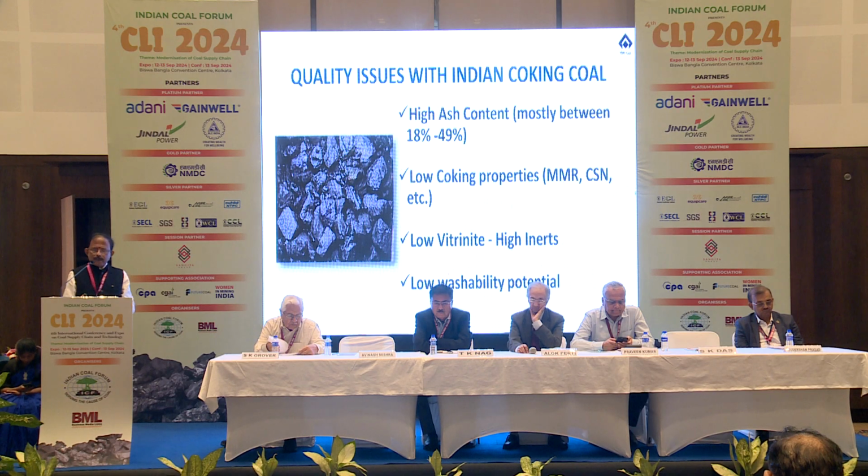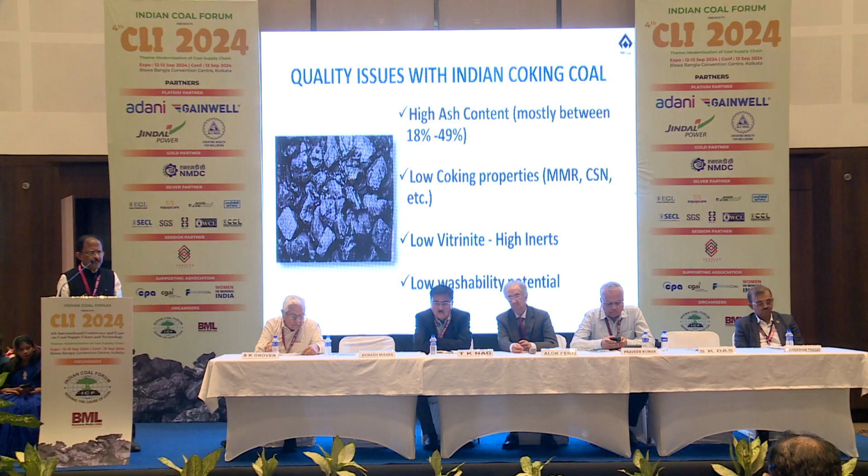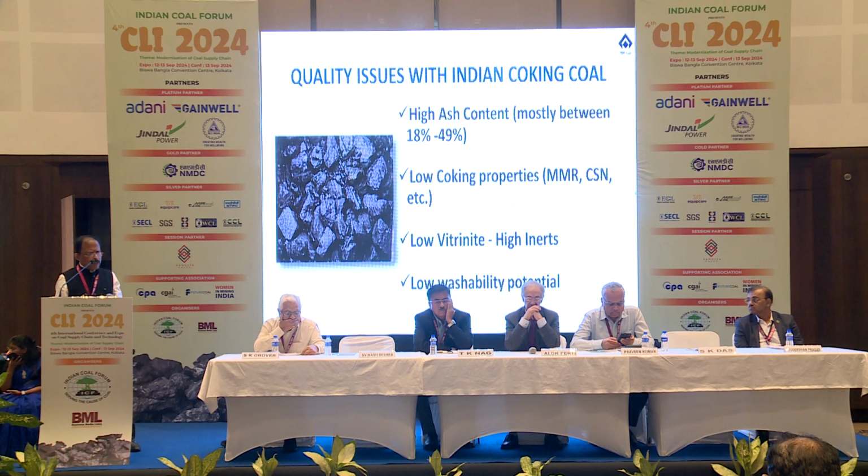Certain quality issues are there with our Indian coking coals. That's why we are switching over to imported sources. It has high ash content, low coking properties, low vitrinite and high inerts, and low washability potential. Because of these drawbacks, we are using only 15% of this indigenous coal, and the rest, 85%, we are sourcing from outside.